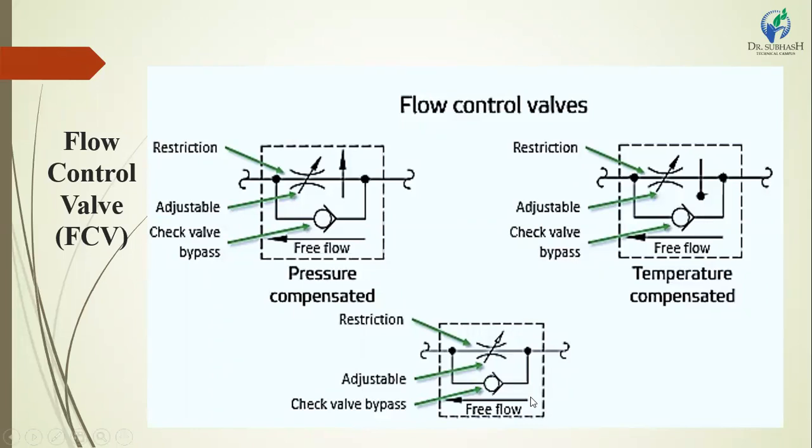These are other different types of flow control valve. Here the flow control valve is a pressure compensated valve. It operates on a pressure basis. Then another is a temperature compensated valve. This is the free flow we already discussed in the previous slide. This shows the flow condition input, and this shows the flow condition output.